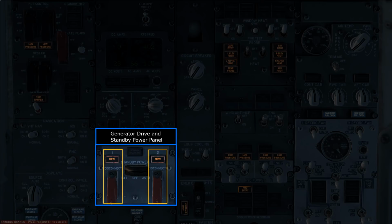You also have these two red guarded switches. If there's a problem with an engine generator, they can be disconnected from the engine. Now flicking these switches is a last resort action, because they will physically disconnect the electrical generator from the engine, and this is an action that you cannot reverse. You cannot reconnect the electrical generator once it's been disconnected. Only a ground maintenance crew can do that, and even then, they would have to pull the engine apart and install a brand new electrical generator.